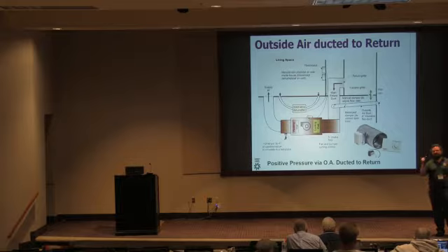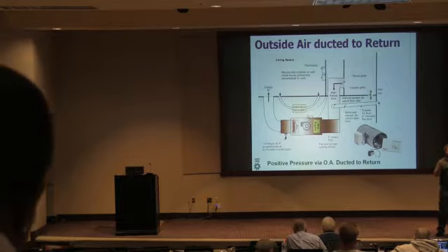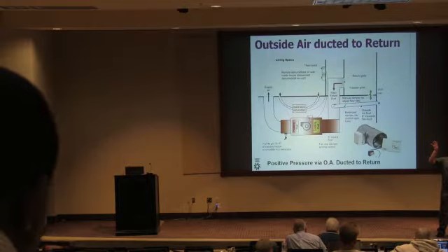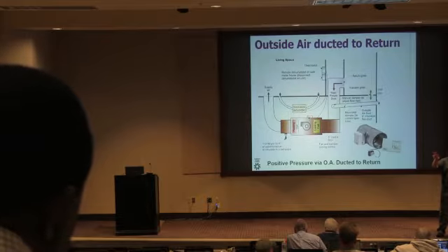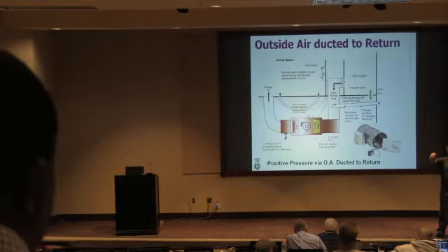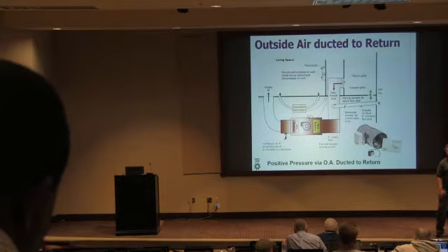I do not recommend this system. What we see as the biggest failure is when they have an open closet in a multifamily situation, and they've just got a free return, and they don't have a fully ducted outside air vent, and they're just trying to dump outside air into that closet. We see a lot of problems with that. At a minimum, that outside air vent should be fully ducted.